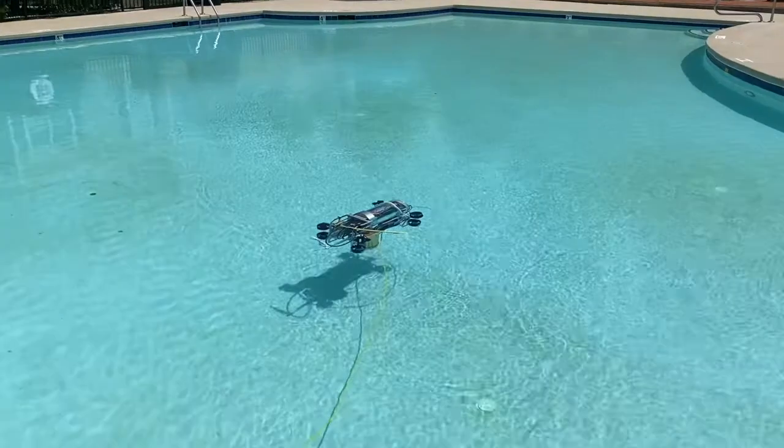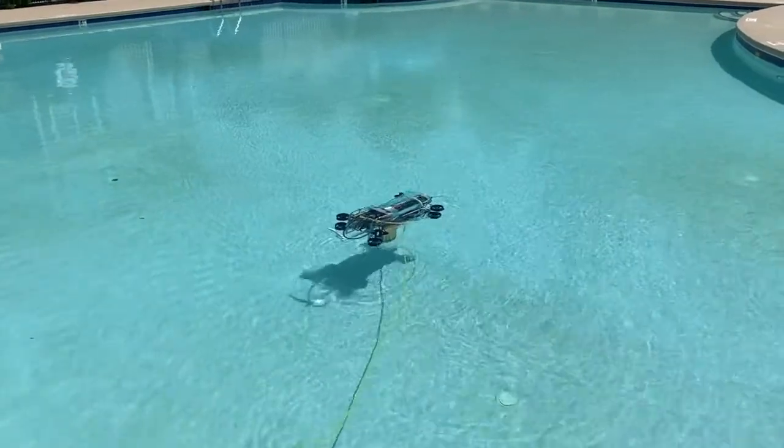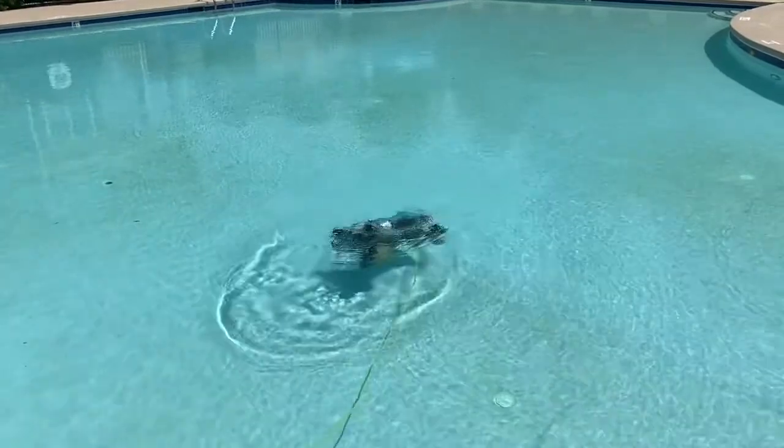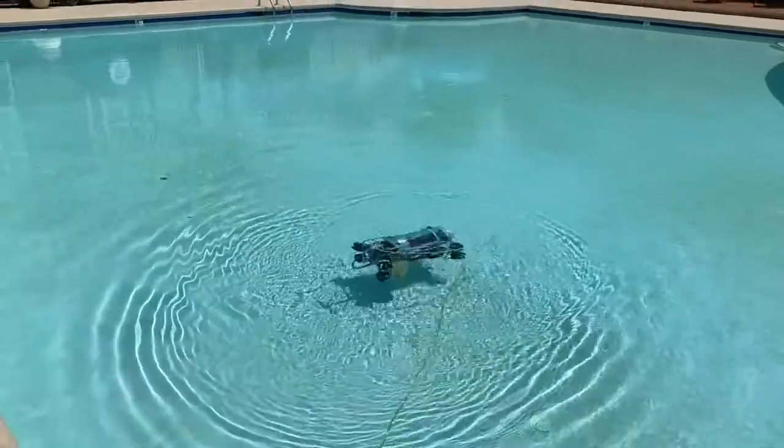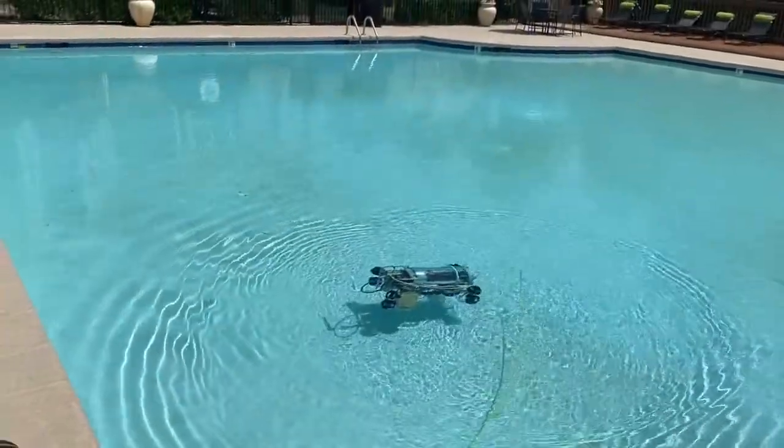Later on in the year, we were able to actually get in some in-person pool tests. Most of our testing results from simulation carried over to the actual pool, which is fantastic because that means that our virtual simulation is close to reality. The robot again demonstrated resilience to currents and disturbances while moving toward a set point. Even the PID constants carried over from simulation. We barely had to tune in person.